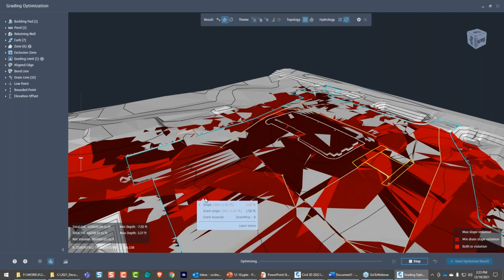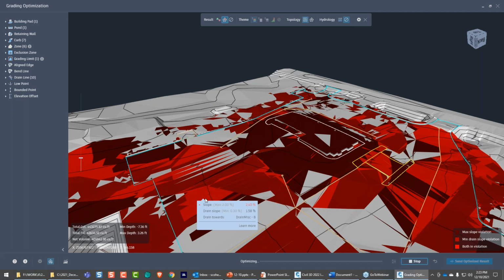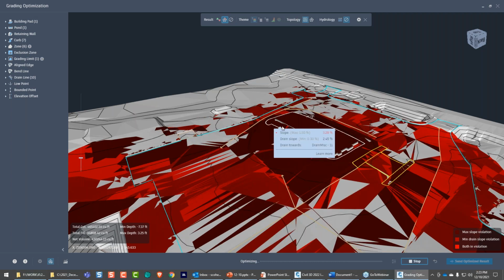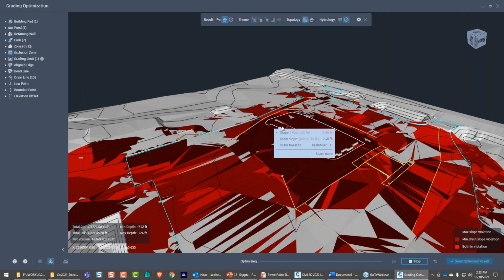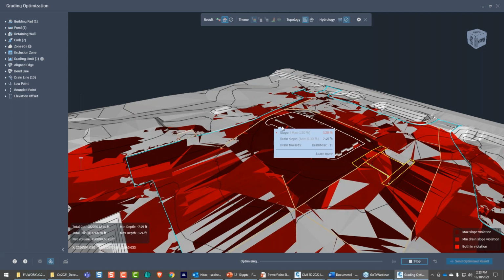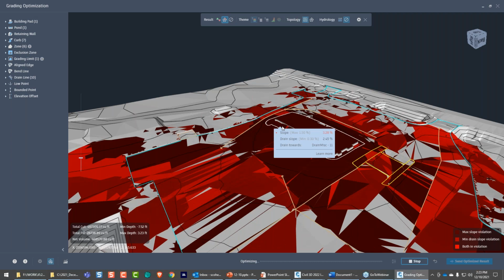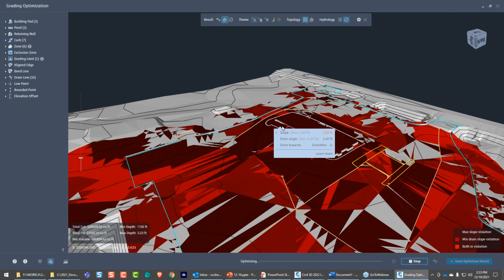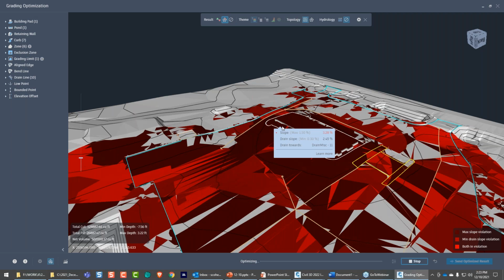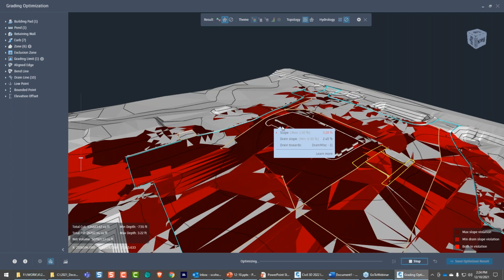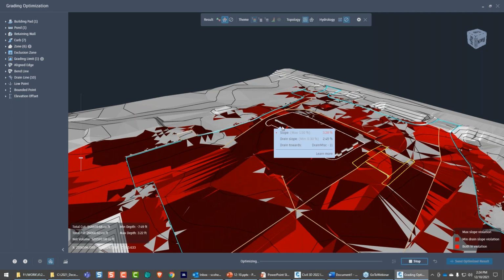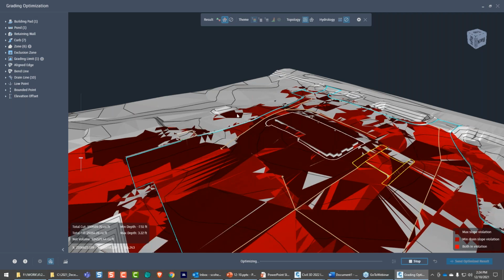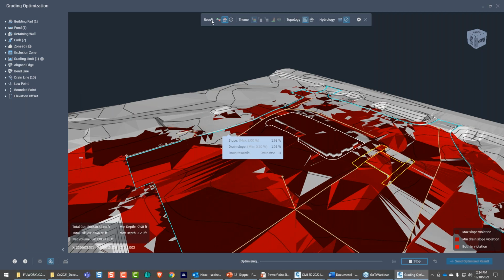Now, if I'm starting to get that kind of stuff in here, then I would freak out. But look what I did for this one. So that's the sidewalk right there. My min is 1.5 to 0.3. I am getting 3.28, so I would let that grade out a little more. Or maybe I would check my zone and make it 1%, right? So you just play with the numbers. Again, don't worry about the whole red all over the place. That was one of the first things I was like, oh my gosh, it's not working. And I realized I'm not going to worry about it, right? So you can just shut this off here. So we'll set that back to none.